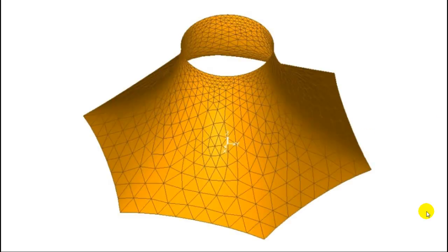Fabric tensile structures are difficult to draw and harder still to visualize. Therefore, a stage of preliminary design usually precedes a structural analysis in detail. The preliminary design of tension structures involves the determination of an initial configuration referred to as form finding. In order to make this process much easier, the special frame and grid model was developed.